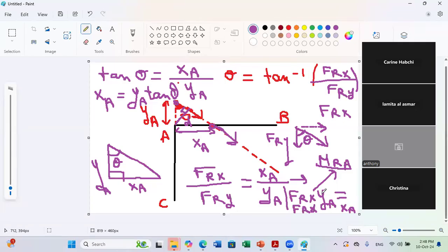And I can relate XA and YA by this method, or also by saying that if I displace a force on its line of action, its moment about A will not change. So once I find one point of application for a single force, I can deduce all other points. Okay. Question on this?